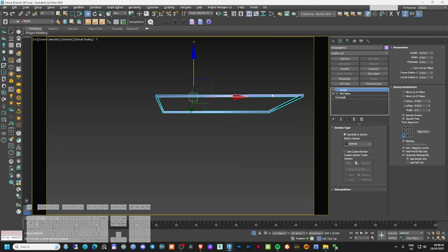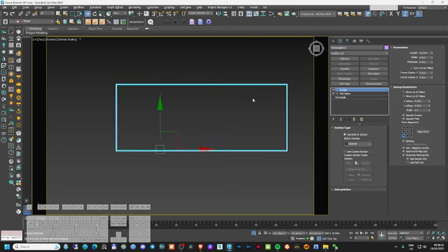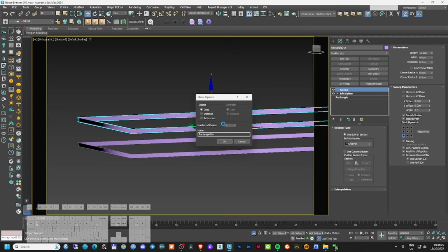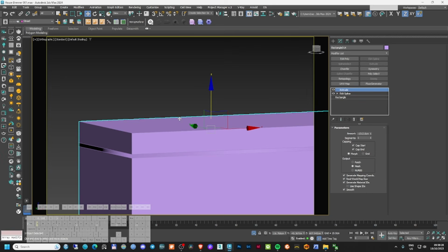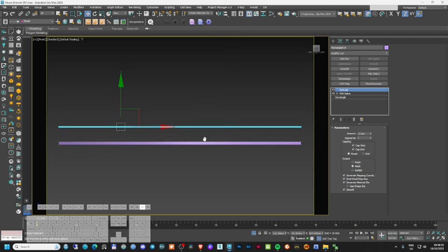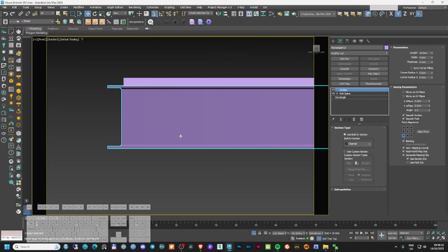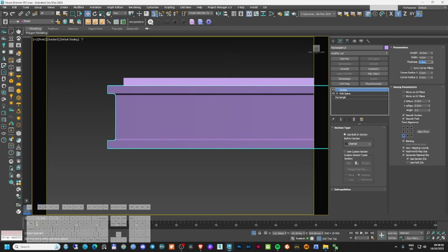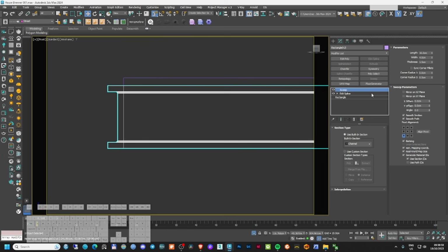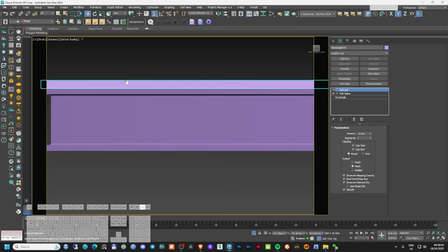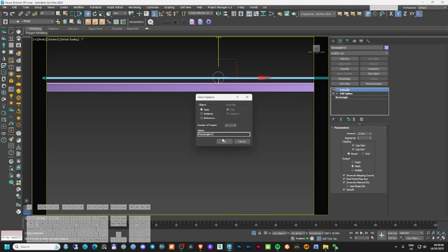And then on top of this profile we're gonna have a surface. Copy, delete this, use an extrude. Let's make it 2 centimeters. This profile here is quite small. Let's change that to thickness 2 centimeters, maybe 1.5. Yeah, and this should go more on the inside like this. Okay, this is looking good. I'll make a copy of this also.